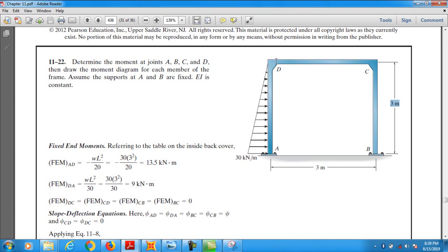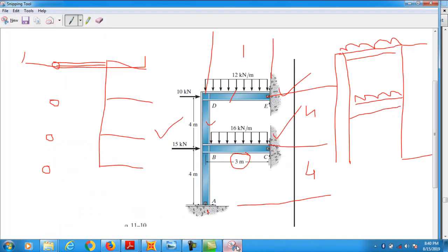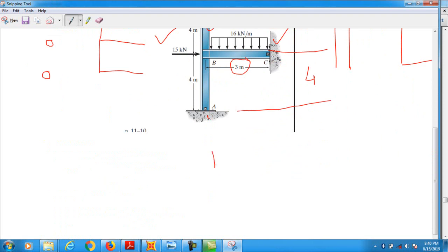Select assign menu, frame loading, distributed loading, and in distributed you will use the absolute distances. So you select this. If you are confused about which side the 0 starts from, you can make 2 attempts, and in one attempt you assume that 0 starts from there. In distributed load, when you are using absolute distances, you have 2 columns, okay.